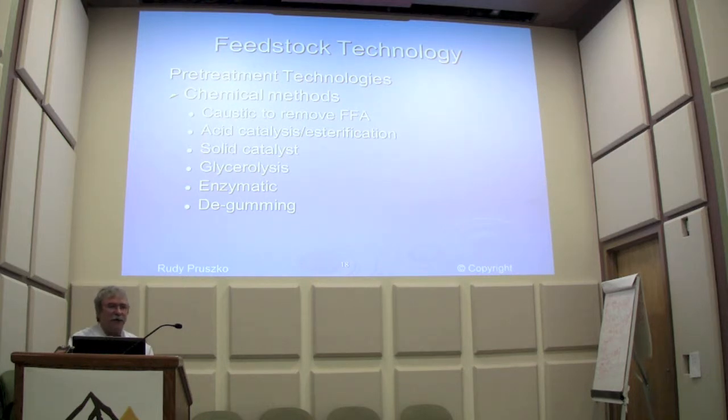You can use solid catalyst. That's an upcoming thing, but you have to understand, when you want to go with different feedstocks, that sometimes solid catalysts get poisoned by metals. And so with a solid catalyst, you want to make sure that you can continue to use it. If it ends up getting poisoned, it's useless, then you've thrown a lot of money away on a solid catalyst. And sometimes they have very stringent feedstock requirements.